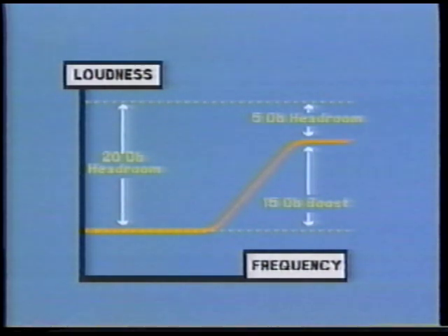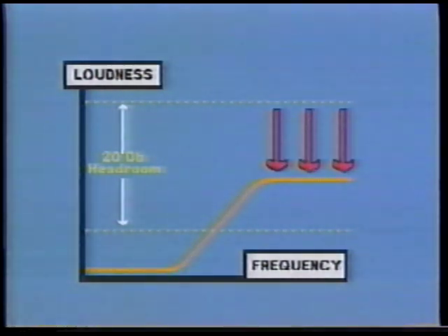To prevent this, turn down the signal going into the equalizer, thus gaining more headroom for the EQ amplifier in the boosted range. If you're mixing, use the input trim to turn down the signal coming from the tape recorder. If the board doesn't have an input trim for the tape signal, turn down the tape recorder's playback. The EQ'd signal will be cleaner and have less distortion.